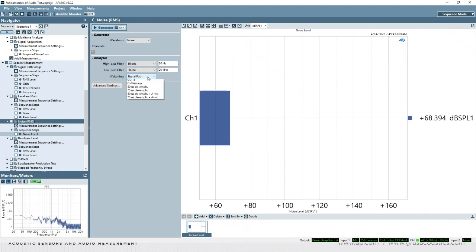And this is exactly where I might say, oh, I would like to apply an A weighting filter to this. So this is now telling me the noise level in this room in dBSPL A weighted. Now you'll notice that this measurement is varying quite a bit, and that's of course partly because I'm talking, but also partly the random nature of noise.